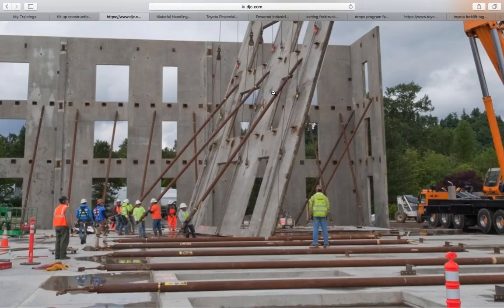So there you go. Let's go ahead and go to the bottom of page 9. Again, a little bit of Groundhog Day here, but we're going to cover it. Keeping all tools clean, sharp, and in safe working condition. Using guards and safety devices whenever they're required or come on any type of equipment. We're going to report all defective tools and machines. We're going to lock out, tag out if necessary. We're going to disconnect and lock out power machines before we service them. Also, we're never going to use compressed air to clean ourselves, right? And if we're cleaning off any surface, it's going to be pressed down to 30 psi or less.